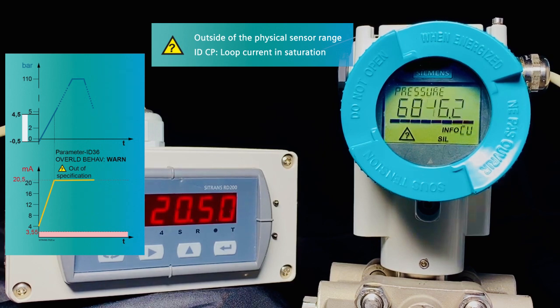The value is outside of the physical sensor range. However, the output current remains in saturation. When I reduce the pressure and I am within the valid measuring range again, the device measures. This means cascade measurements are possible with the setting warning at parameter 36 overload behavior. Please note that you must take appropriate measures in the warning mode to prevent overload of the measuring cell.